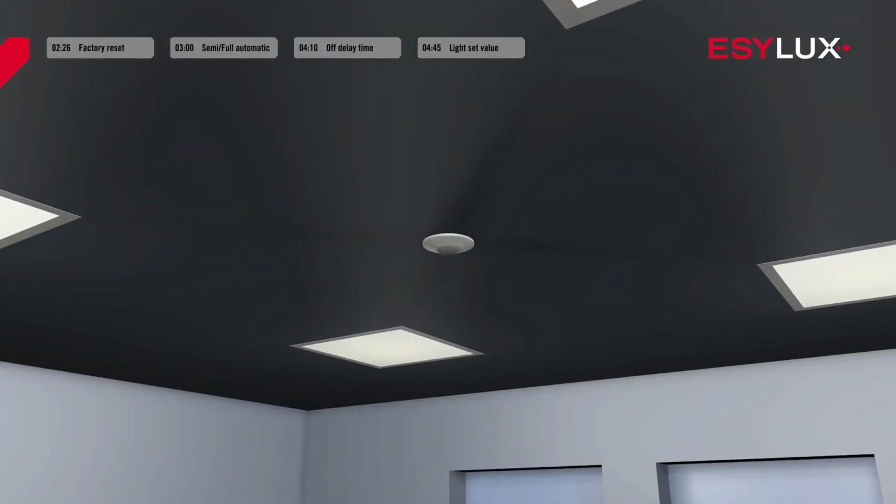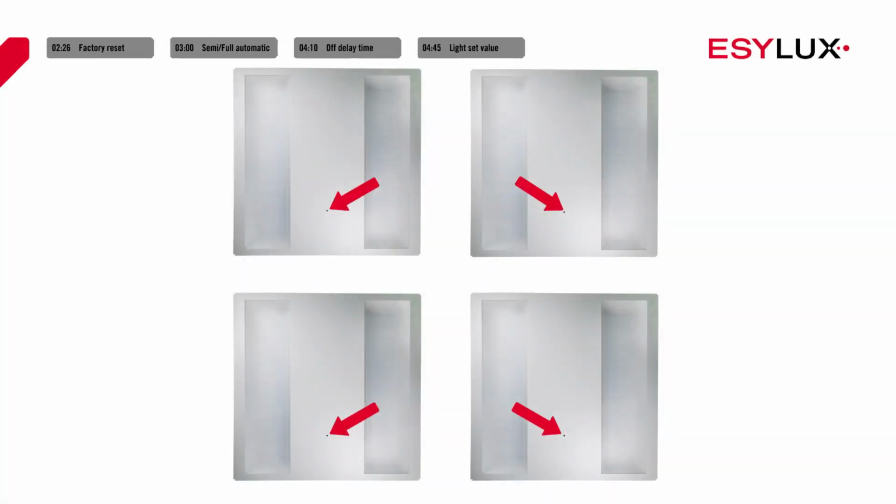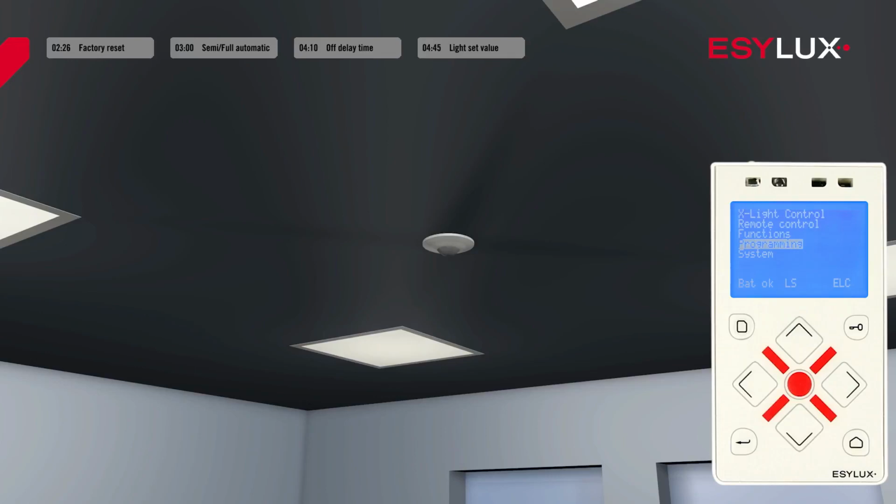Every presence detector has a light sensor, which you can use to control the brightness of a room. Lights are also available with additional light sensors. These lights can detect and adjust the brightness of a room with even greater precision. If you use lights without additional light sensors, then make sure that the light sensor of the presence detector is activated.